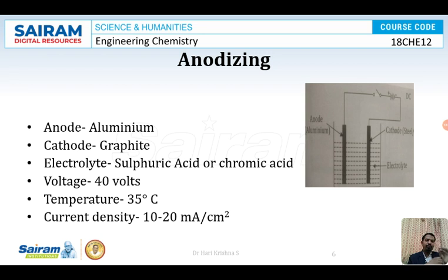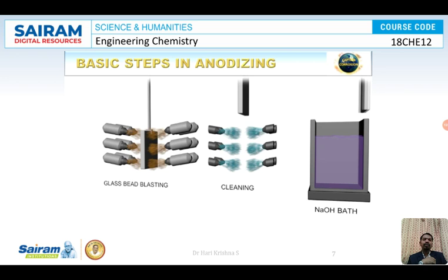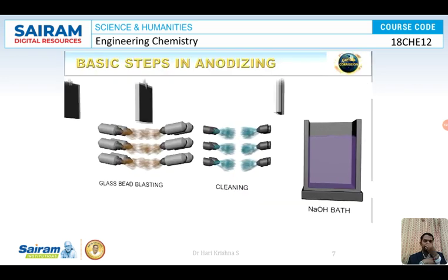If you want 0.1 mm thickness, we vary the voltage and the time duration. If you want more thickness, you conduct this process for a longer duration; for a small thickness, the duration will be less. So let us see a small video on how anodizing is done.